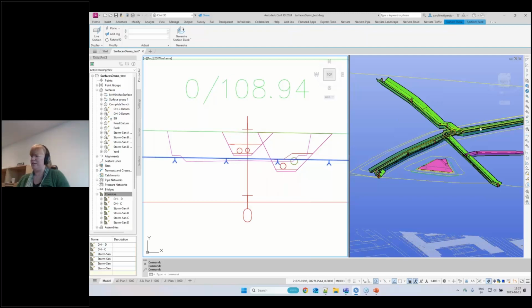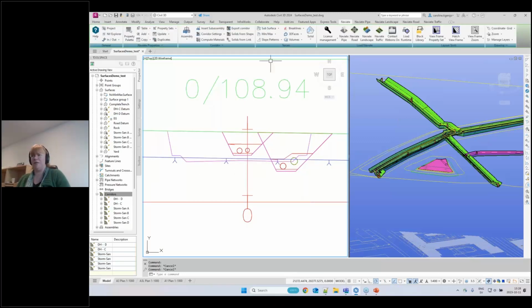This is a section on my corridors. I only want the rock volume that is below the road datum. It is very common inside projects, if you have a rock surface and a road together with it, that you need an adjusted rock surface that is the lowest of these two. That is something my customers encounter very commonly, and it's the same method, the same functionality, still the MinMax that you do.